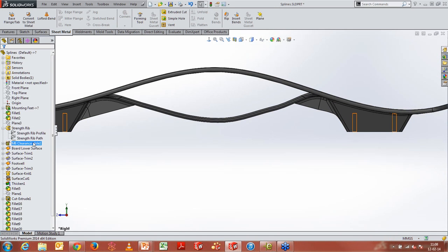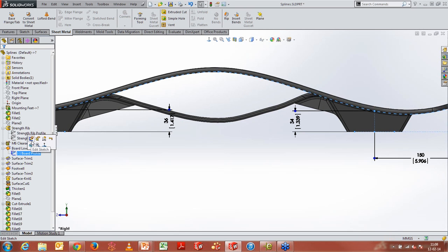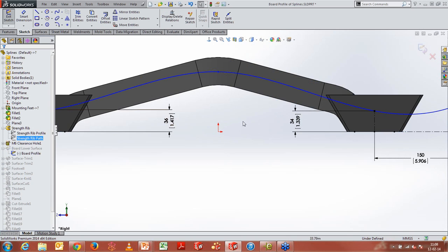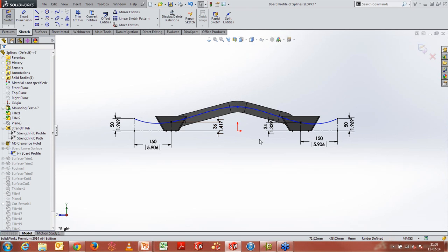Okay. Moving on, like I told you, there's a new option for style spline as well. But before I do that, I want to showcase something new: dimensioning for splines. Over here we have a spline which we can try to constrain, but it's not possible in previous versions.